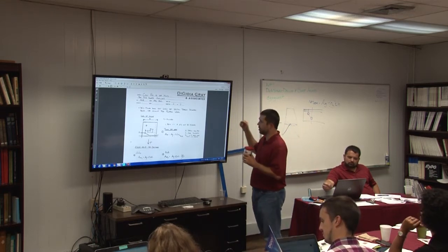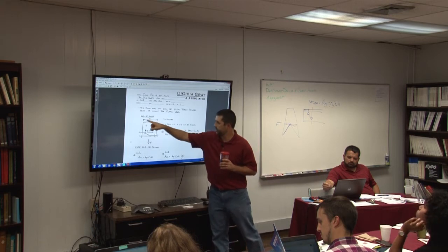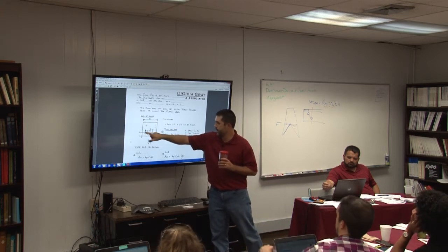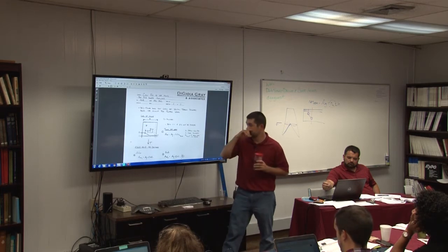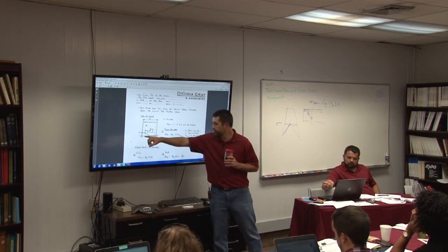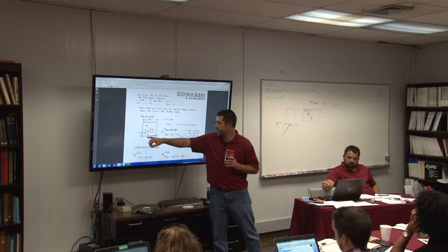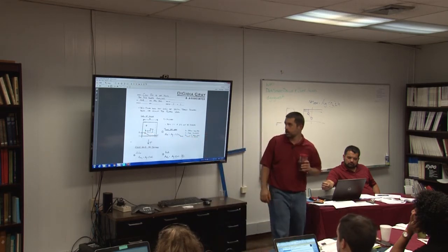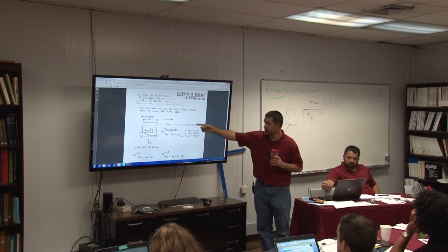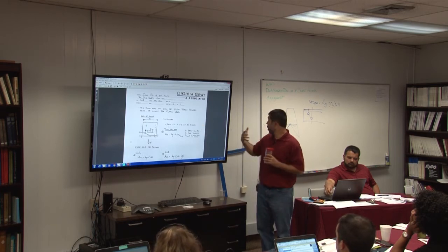What we're looking at is very similar to what I've drawn. I've got, in this case, a staggered bolt pattern, and I want to investigate 2 different potential failure planes. So 1-1 is straight through one hole, and 2-2 is along this staggered pattern. I've got to check them both.